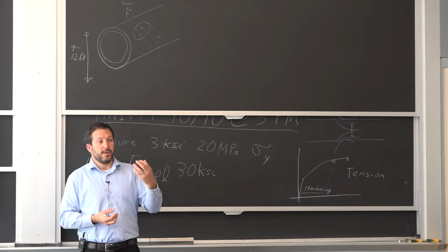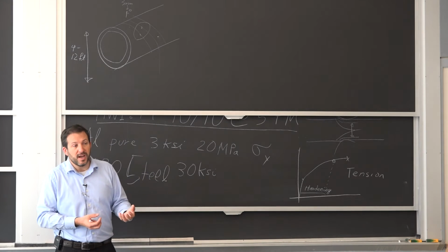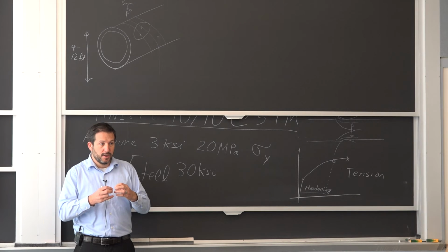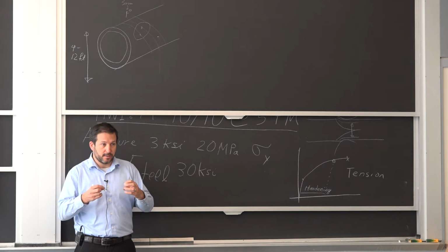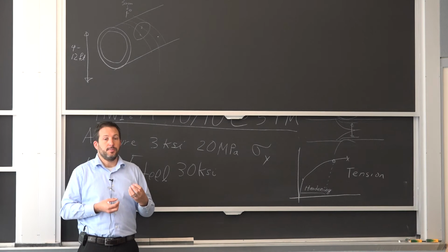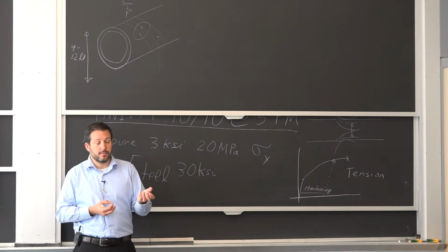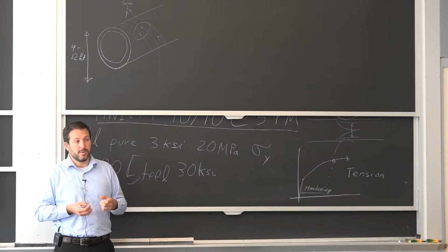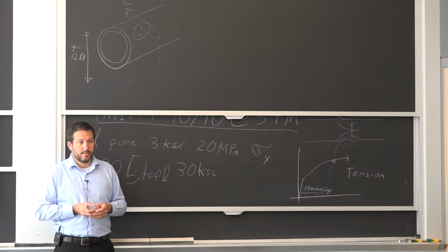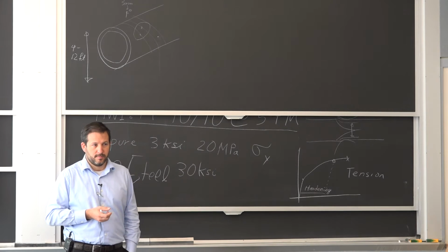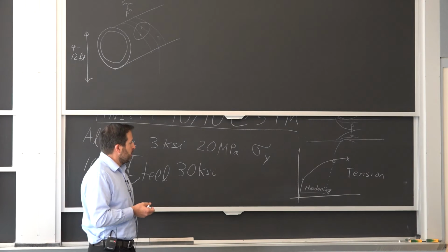And that's how you get it 2 or 3, 5, up to 5 times higher yield in compression. Then when you try to pull on it in service, it's still that 5 times stronger, but it's going to be able to deform, let's say, 4 or 5% now as opposed to 30% before it snaps. That's the big difference. So this doesn't apply for the rolling, right? This diagram. No, not at all.